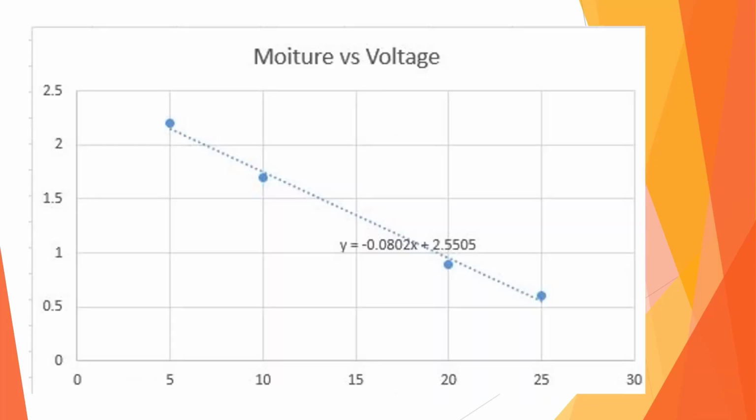Now a curve is plotted for water added versus voltage observed, and a relation is established and implemented to calculate percentage moisture. Thus we can see that moisture sensor array can be easily constructed using E-LAGORI boards in about 20 minutes. Data can be sent to a mobile using Bluetooth protocol. In the next block we will interface a thermoelectric cooler.